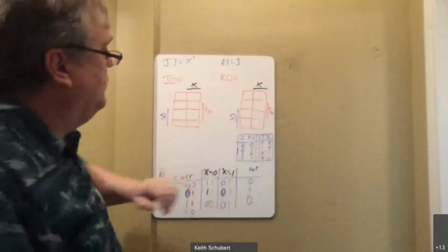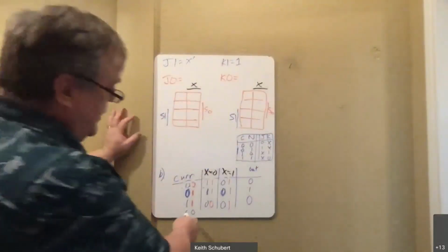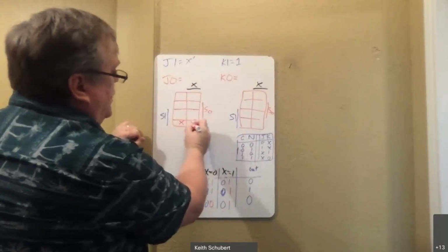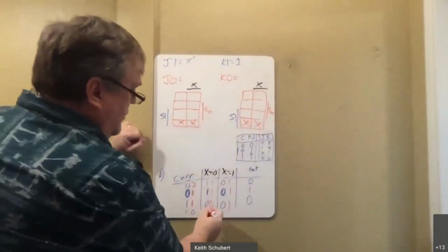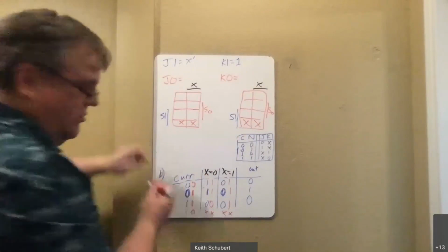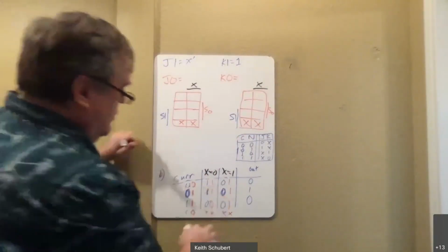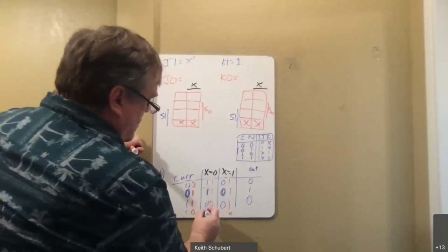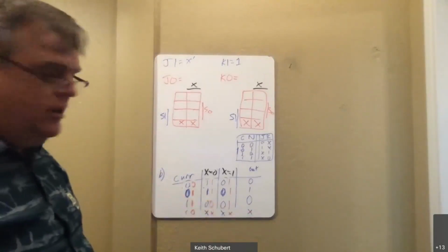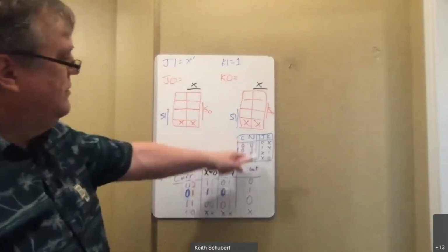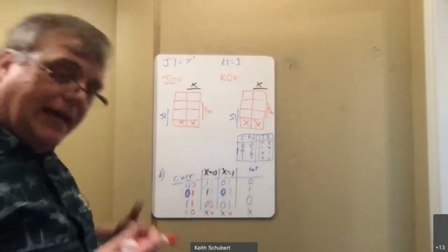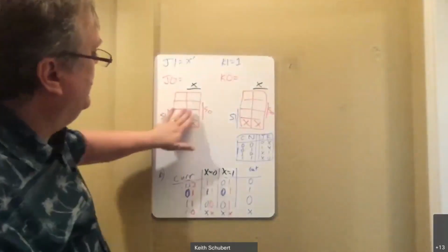So everything in here is going to be red. Since we've already made a notation on this, that this last state, 1, 0, which is this bottom one, I'm going to pick don't care. I'm just going to write the don't cares in, because that's true for all of them. I made that decision for that last line. So the X's, I don't need to worry about it. I don't care what it is, so I don't even need to worry about that table. I've already got X's. And X's are good for design purposes. All right, so I only have to worry about the upper 6 here.